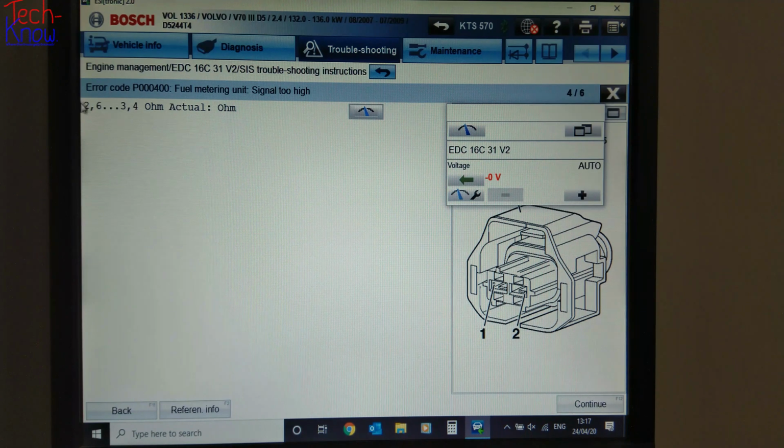So moving further forward, here's my electrical value here, that it should be between 2.6 and 3.4 ohms. Once again, if I click this button, it now changes the voltmeter to being an ohm meter. And as you can see here, it's saying it's open circuit. If I jump that across, it's saying it's open circuit, it's exponential ohms, and that's obviously not going to be correct.